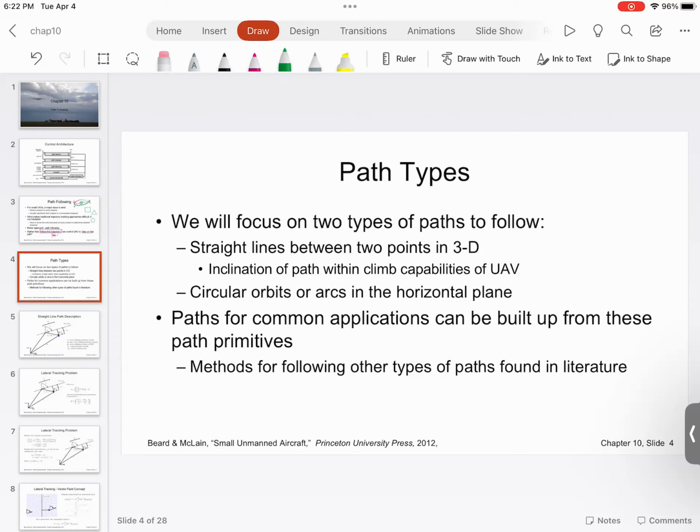If you look at the MATLAB path designer function in the assignment that I asked you to use, it uses the exact same approach. It constructs the path using a straight line and a circle. So again, about 80% of the time you will be able to construct the path using a simple straight line segment and an arc segment.